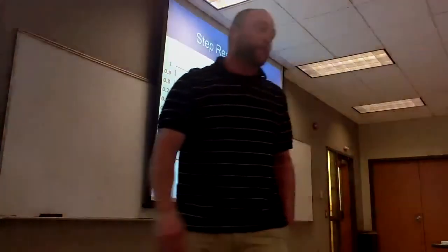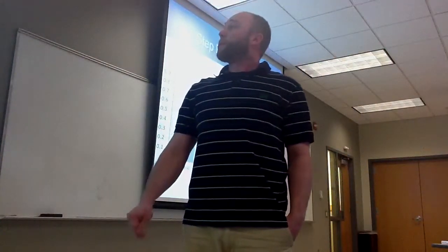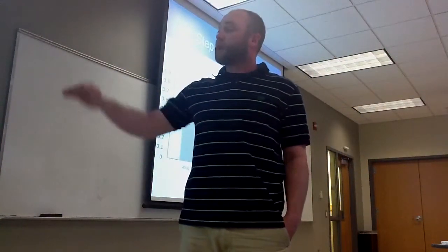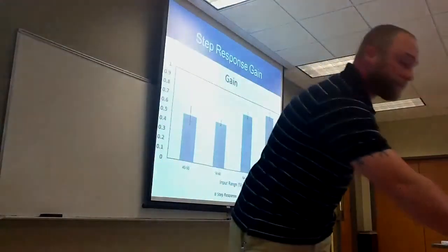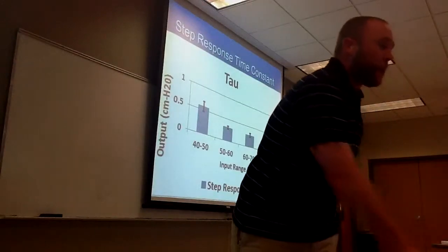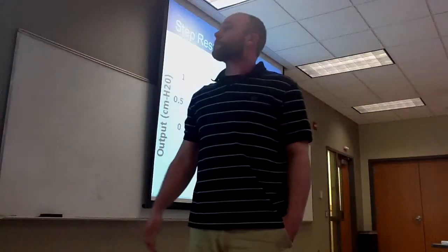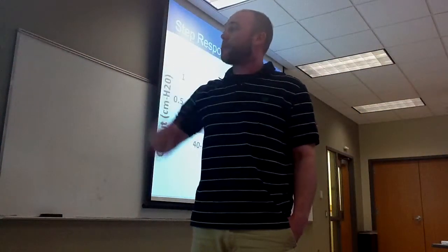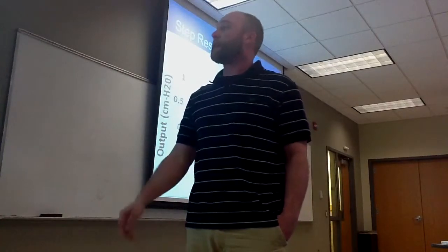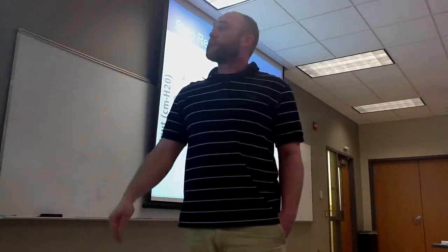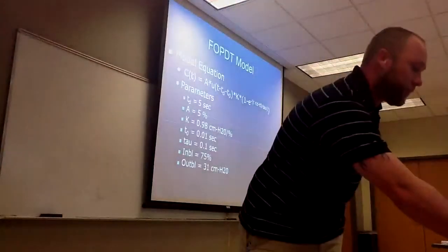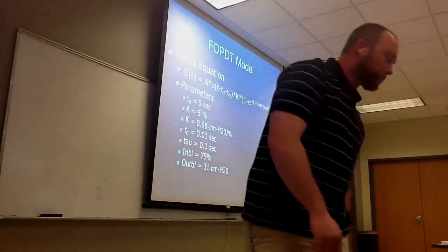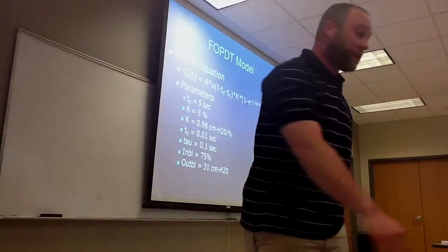Step response. Here's our gain, which slightly increases as the input range goes up. Our tau between our systems, 40 to 50, 50 to 60, 60 to 70, and 70 to 80, remains somewhat the same, tau being our time constant.